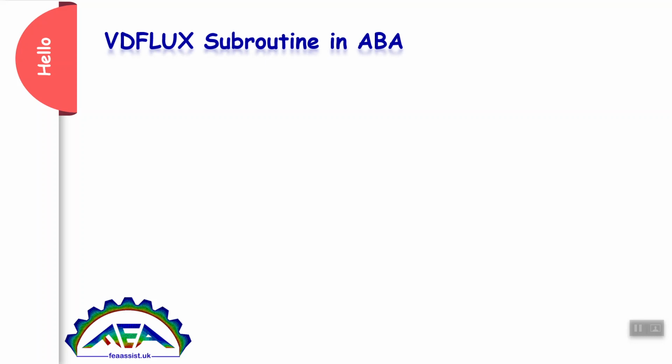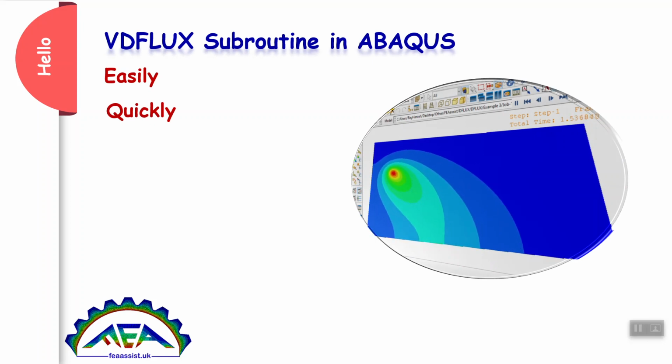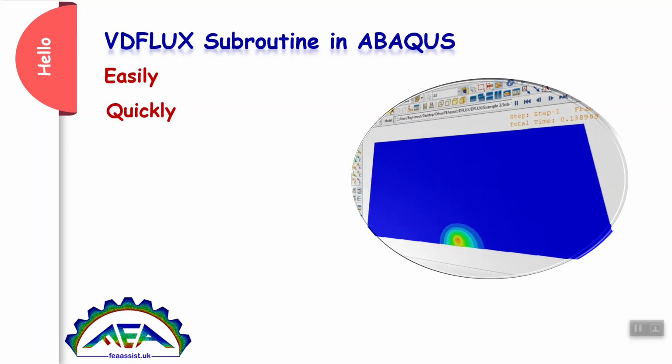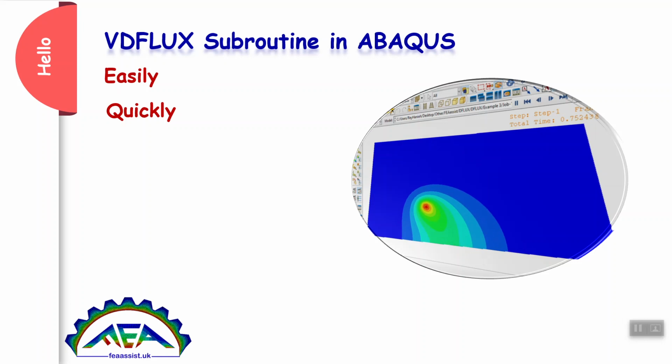Hello, you want to learn the VDFLUX subroutine in Abaqus easily and quickly. Actually, VDFLUX is a subroutine to have a movable heat source on your plate or on your sample, which is used in some processes like welding or additive manufacturing.